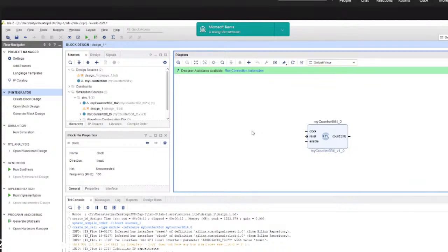Because in Xilinx Vivado, by default we have an intellectual property IP core in order to generate a clock signal with a desired operating frequency. So now I will add that IP core from the existing IP repository provided by Xilinx Vivado. So how to do that?